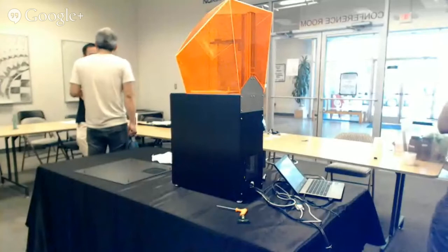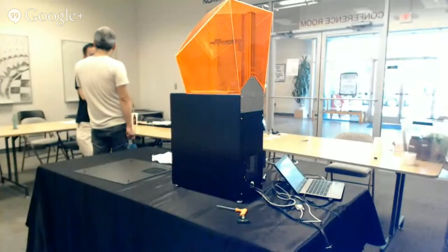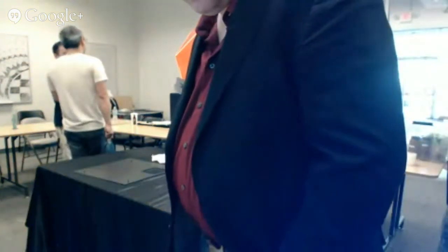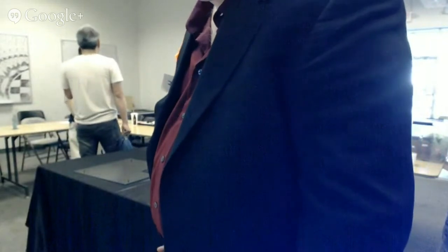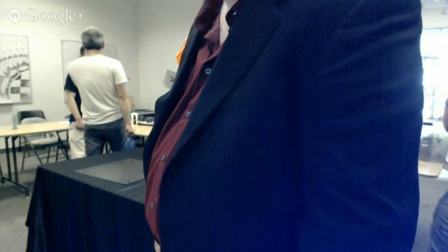So how many times would you put the injection mold into that thing before? I don't know. A PolyJet is really the best thing to make these resin molds out, not stereolithography, because it's a challenge to make a mold like this in stereolithography because of all the separation forces. This came out pretty well, these two guys are pretty flat. But getting perfectly gigantic flat objects is hard.